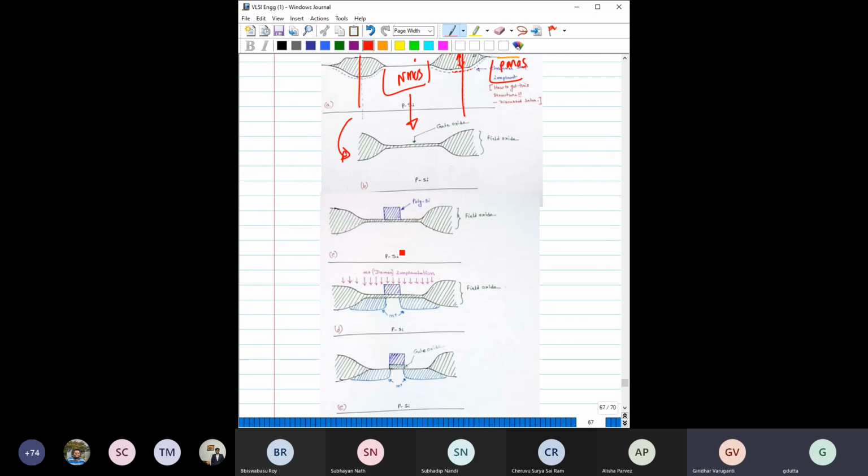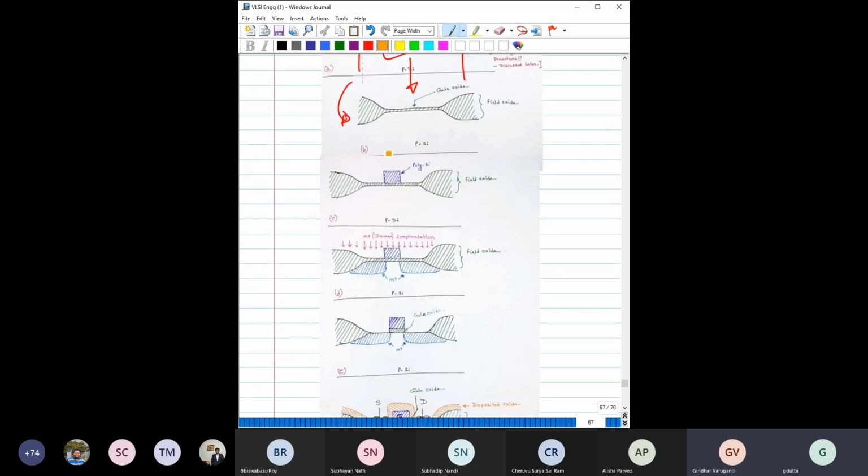All right. Okay. Then after that, what we have done on this, we have already this gate oxide. So on top of it, I have placed one polysilicon gate. So here you can see that metal is not possible. I have not used metal. I have used rather polysilicon as a gate. There is a reason why polysilicon is required, why we cannot use metal. I will just come to it, but first see the total process step.